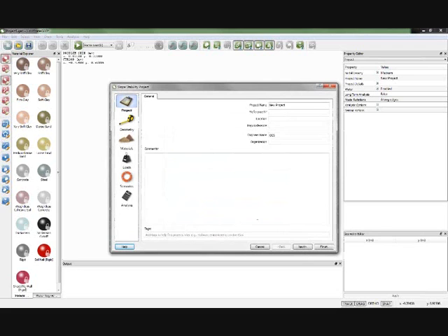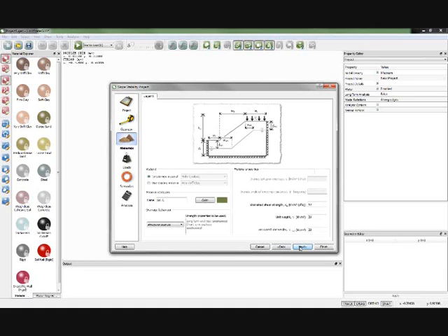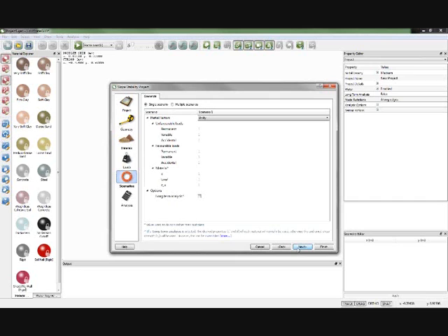So you get a wizard, and as you go through this, I'm going to go through this fairly quickly. You get asked, so you can change the geometry of the slope. I'm going to accept the defaults. You can add a water table if you wish. You can define the properties of the soil in the slope, so you can define an undrained shear strength and also its unit weight, and also, if you wish, drained parameters. In this particular wizard, you can put a surcharge. We'll leave that at 0 for the moment.